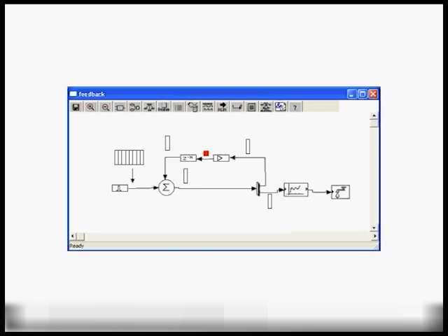Now notice in this case it has a sample to output, so in the next schedule for the delay block it would process the output sample. And the add block again will see a sample here and process one of these samples, one more of the samples output by the impulse response. So we see that feedback actually gets kick-started. We don't have a deadlock situation, and the simulation proceeds.